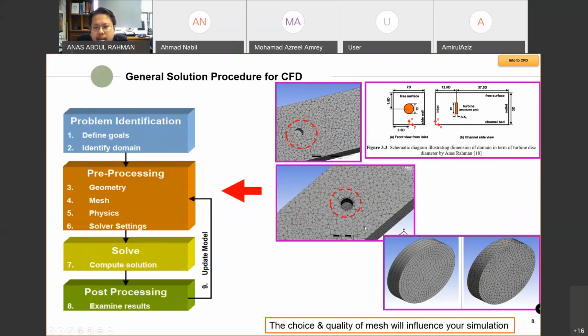On the other hand, you have localized meshing in ANSYS, meaning that because we know that this is the object of interest, and we want to see the flow interaction between the inflow and the flow around the object, we need to make the mesh around the area of interest smoother or more refined. So instead of global meshing, we use the localized meshing setup.